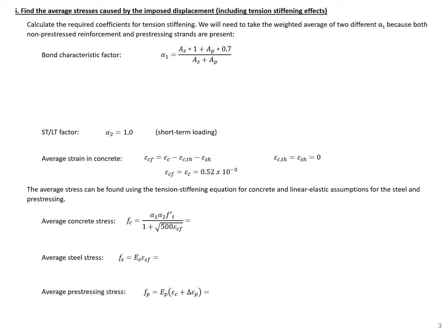Because we have both pre-stressed and non-pre-stressed steel, we need to take a weighted average of the pre-stressed versus the non-pre-stressed steel.